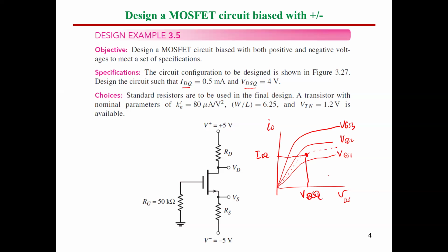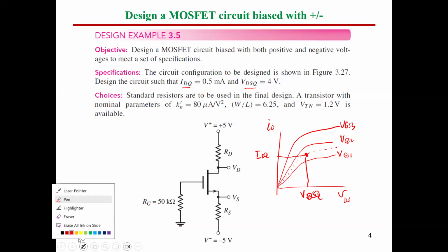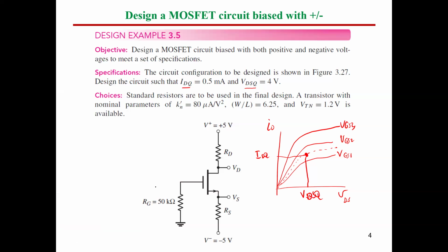And this means now, guys, you have a certain operating point. So the certain operating point, guys, is going to be the intersection between what's called load line and characteristic. So this is the load line now. So this is a certain value of ID.